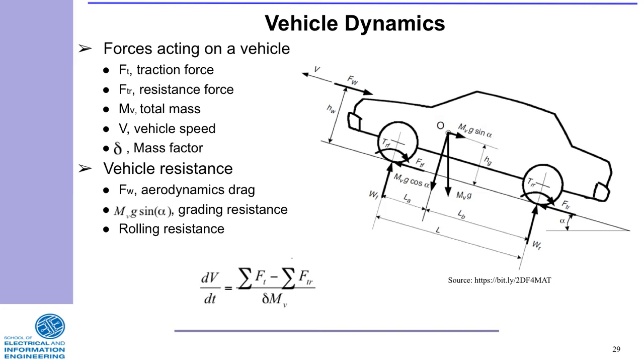And then the other force is the one that's acting normal on the tires, and we can see that it's also influenced by the gravitational pull, which means the weight or the mass of the vehicle. But as we can see, the higher the inclination or the gradient, the less the normal force on the tires, but the more the gradient force on the vehicle.